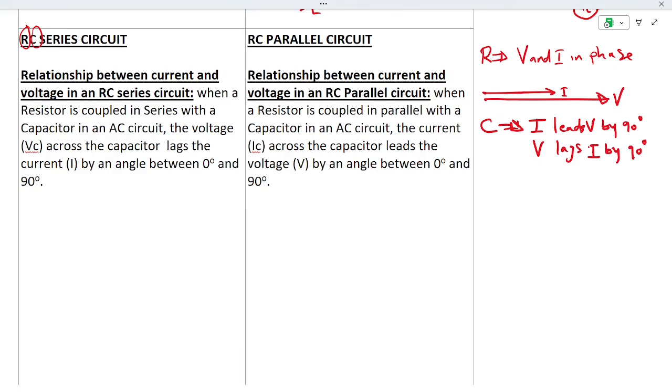You remember now. So now, how is the phasor diagram? The phasor diagram is going to have the current as point of reference and the voltage pointing down like that. So there is our current and there is our VC pointing down like that. So that is our drawing, 90 degrees there. Now let's go to the circuit.